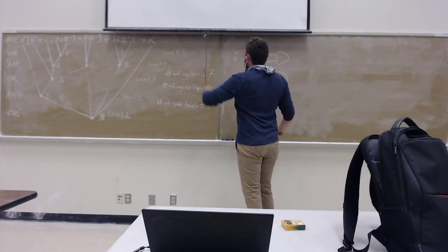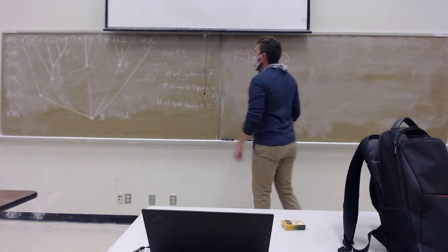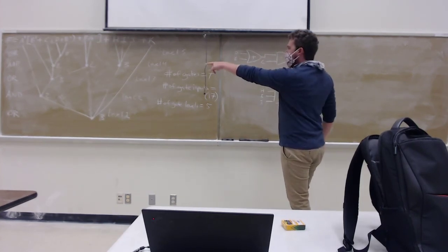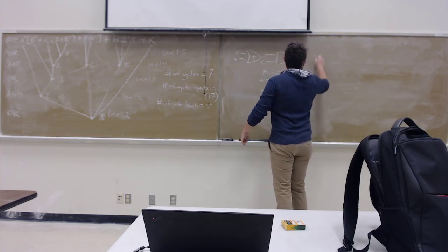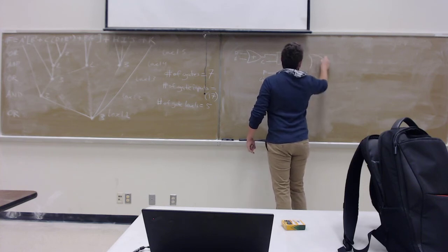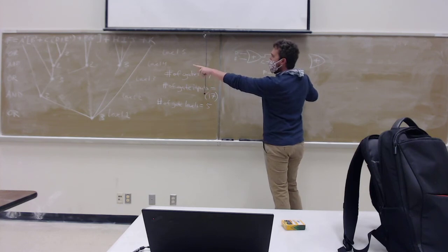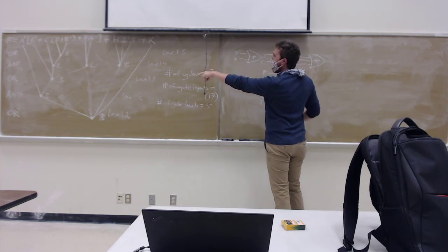And the third one was H, I prime, J. All right, those are AND gates. Next up, we had a level of OR gates. It only had one OR gate in it, and that had 2 of our AND gates, specifically these 2, and B prime.